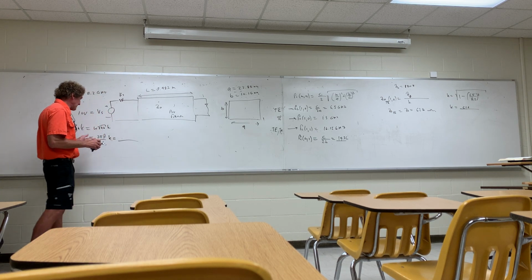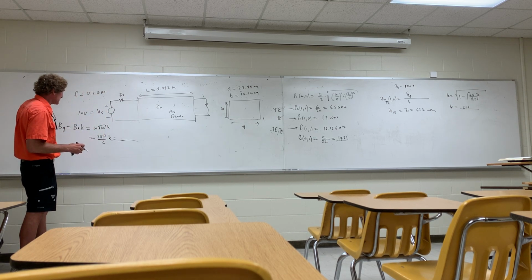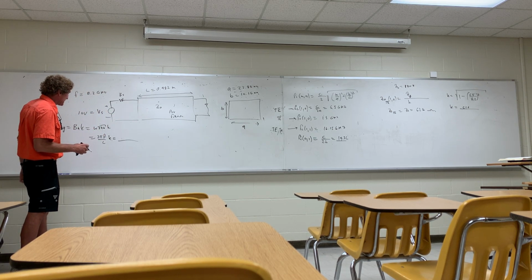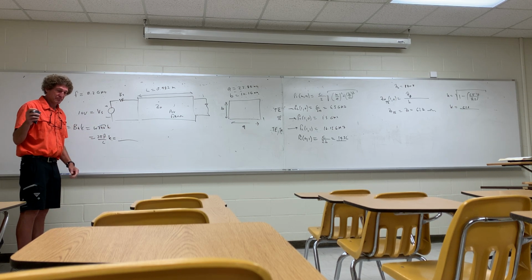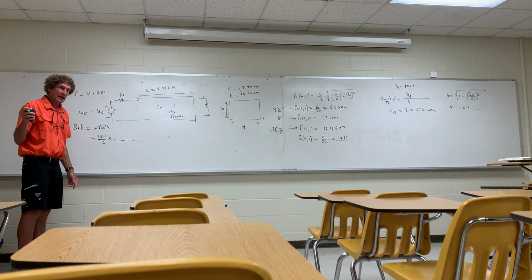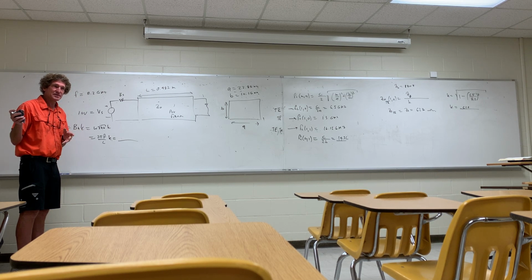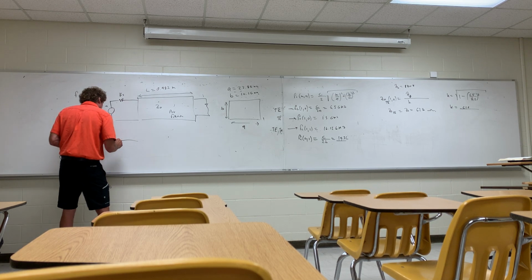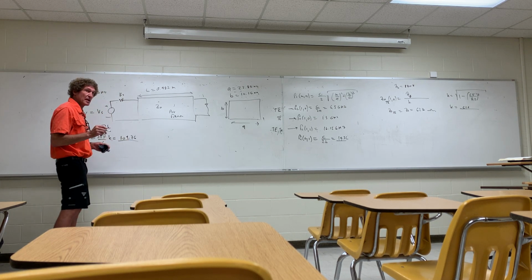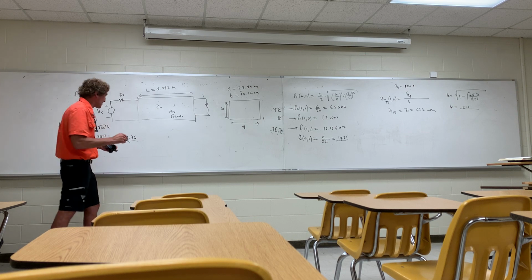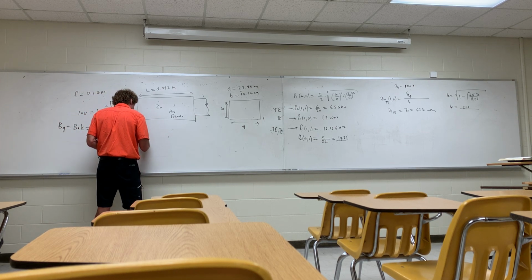And straightforward, 2 pi times 8.2 times 10 to the 9th over 3 times 10 to the 8th times that value of K. And can somebody give that to me? It's 104.76. All right, now everybody check yourself. Make sure you get this. This shouldn't be a difficult calculation. 104.76. And that would be radians per meter, would be the units of this, right?